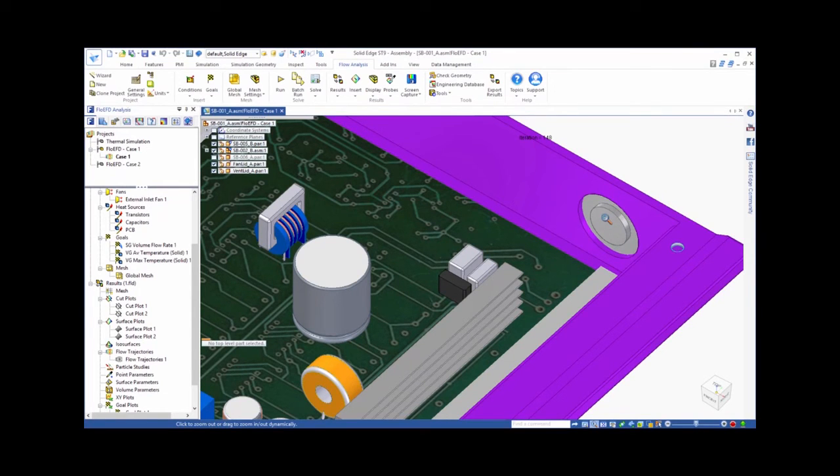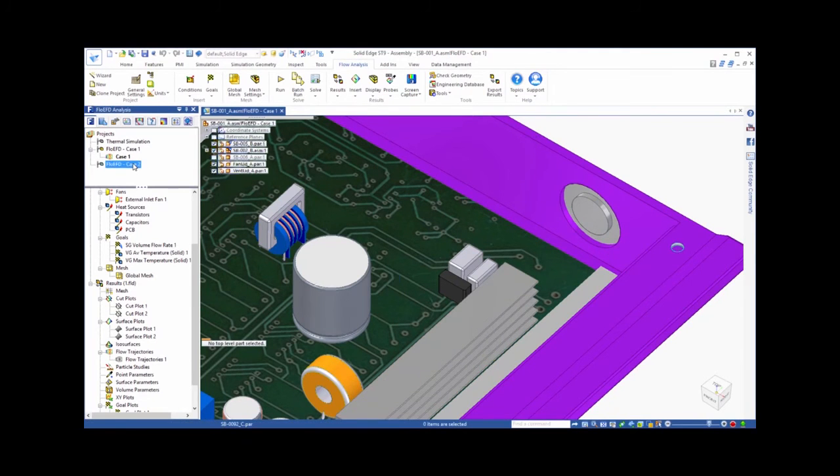One of the ideas that we would like to test based on our first solution is to shift the fan slightly towards the center of the amp. We are hoping to divert a portion of the incoming airflow more towards the central region of the board while still maintaining strong flow through the heatsink. Additionally, we'll go ahead and increase the length of the heatsink fins to further help cool the transistors. So we have set up a second family of assemblies member in Solid Edge that reflect these design changes.